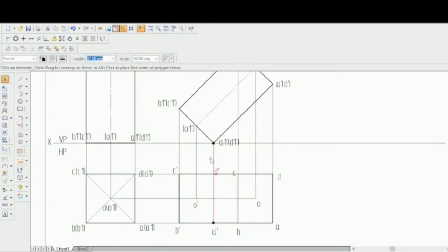So what you can do for that is, you can trim this particular one, or you can use this split option also. That is also another good idea. So select this, so split at this position. Where I am placing the cursor, that particular line got split. So now if you select this, only this part has got selected. So you can just make that hidden. Select this as something around 0.5, so that you will get a thicker line.